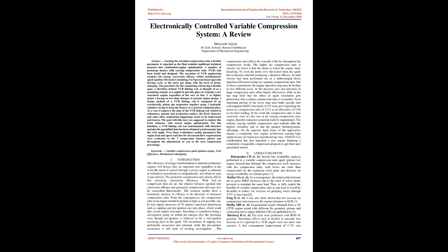In order to improve the design of the VCR connecting rod with regard to robustness, weight, and production costs, the dynamic behavior and other occurring phenomena need to be understood and known. The goal of this project was to explore this dynamic behavior experimentally. For this purpose, a VCR connecting rod was instrumented with sensors, and the measured data was acquired synchronously to the crank angle. Over those tests, relevant parameters like engine load and speed and the oil supply flow requirements were evaluated for the two compression ratio phases and during the adjustments from one compression ratio to the next.